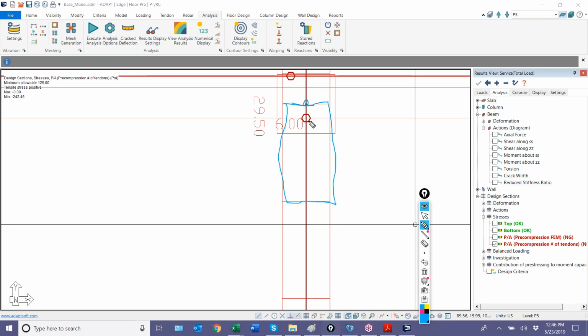So what the program is doing is when we discretize the tendon to the frame elements, we basically break this tendon into a bunch of segments and consider it as an internal resisting element for the solution. This tendon is actually being truncated. It's getting cut off here. We're pushing it to this location right there.